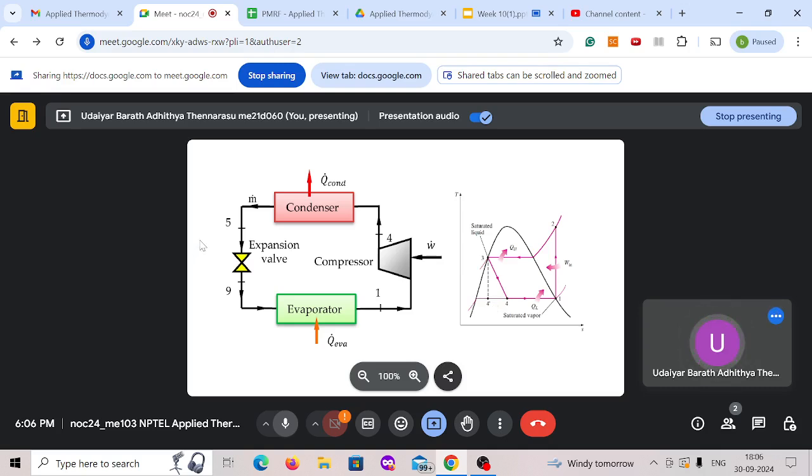So you are moving away from moving components. That is one advantage: in the case of a valve, there is no moving part, so there is increased reliability of the system. So going with a valve is an advantage. Another advantage is that you are operating here in a two-phase region, so you don't want a turbine there.